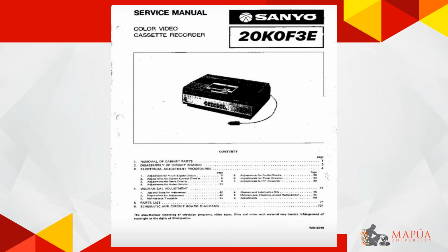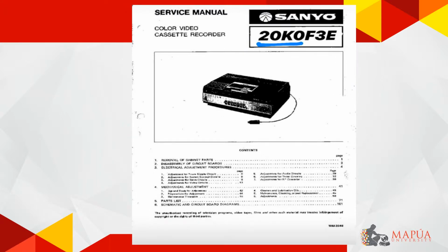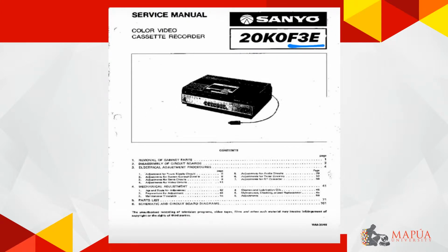If you have ever obtained a license from the FCC or spent time looking at your radio's manual, you will notice a 7-character code like 20K0F3E. It's not there for decoration. It actually means something. The first four characters in the example above stand for occupied bandwidth in kilohertz. So, 20K0 would signify 20 kilohertz of bandwidth. The last three characters signify the type of emission. F3E stands for analog voice.